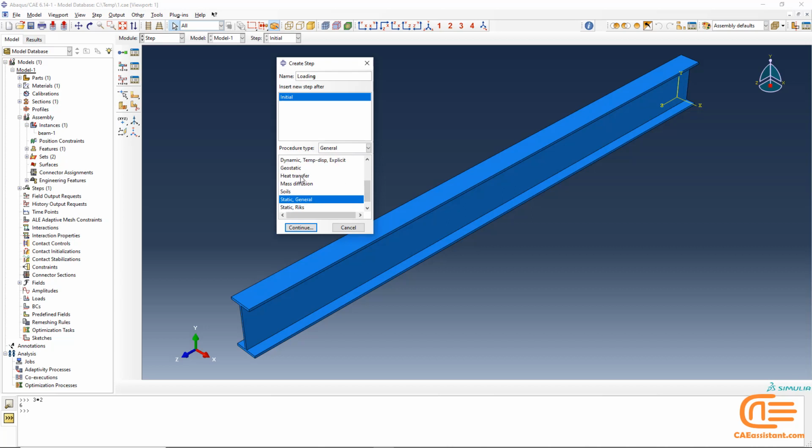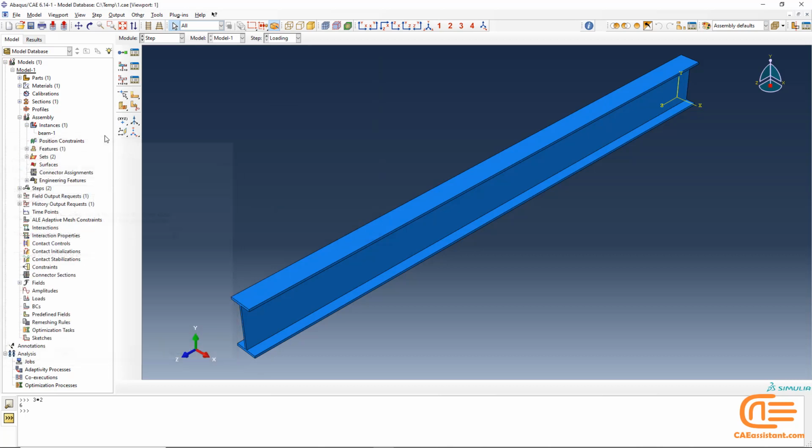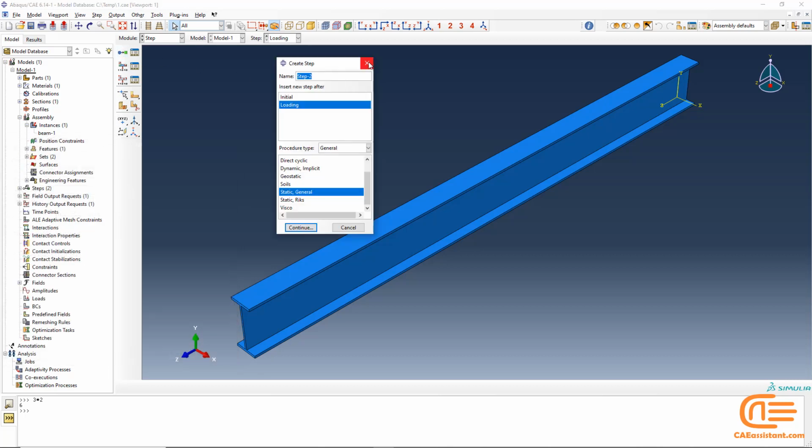You can change the analysis procedure from step to step in any meaningful way, so you have great flexibility in performing analysis. Since the state of the model, such as stresses, strains, temperatures, and so on, is updated throughout all general analysis steps, the effect of the previous history is always included in the response for each new analysis step.